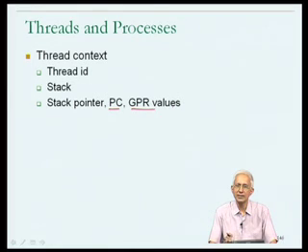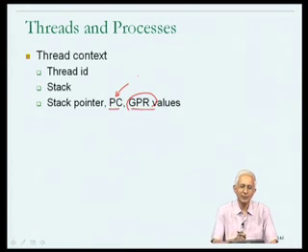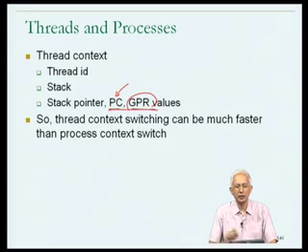If there are two threads and they are viewed as separate threads of control, executions inside the processor, and I can switch from one to the other, very clearly the value in R1, register 1, from the perspective of one of the threads, is not going to always be the same as the value in R1 from the perspective of the other thread. Similarly, as independent threads of control or flows of control, they will be executing different instructions. Therefore, they must have separate hardware context of this kind, but that is pretty much it.